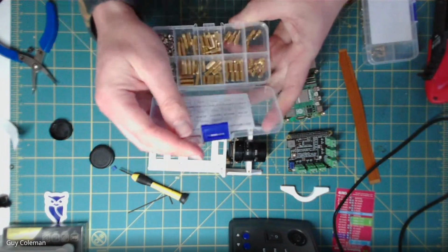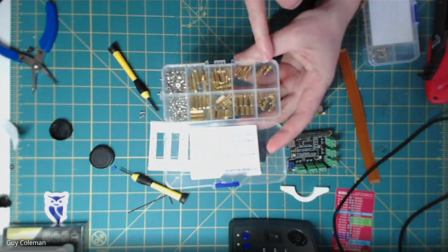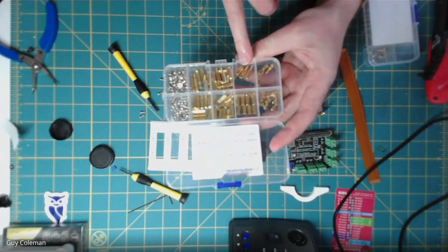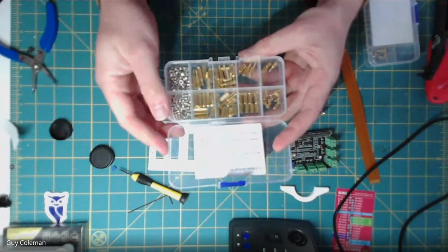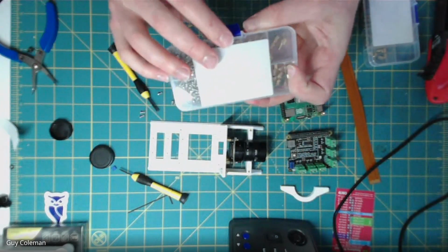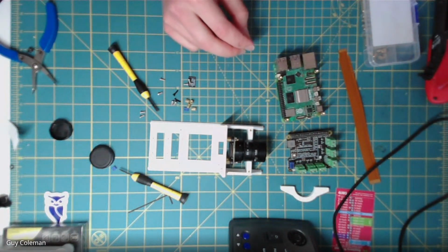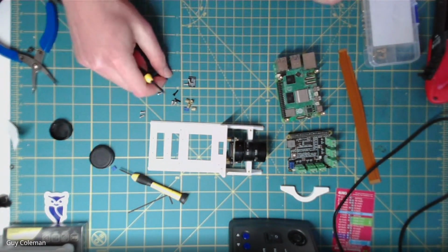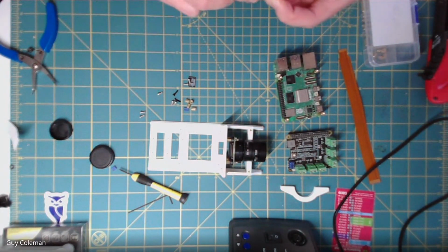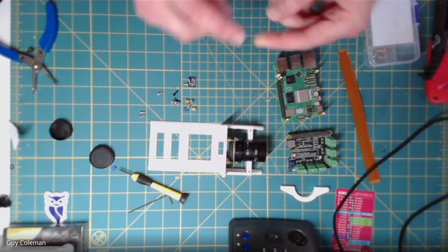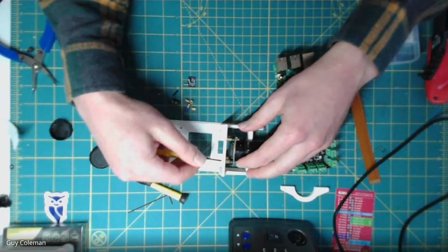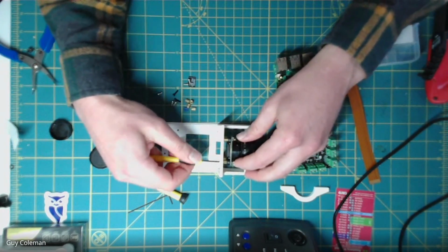They come with a range of different standoff options, because these are the ones you use for the Raspberry Pi base. These are for the camera, and then also your nuts and your screws to fit. I also use nylon ones sometimes as well. I prefer brass, just for longevity, and the nylon screws tend to strip much easier, particularly if you want to tighten it down hard so it doesn't come loose. Anyway, use the screws to tighten it in.